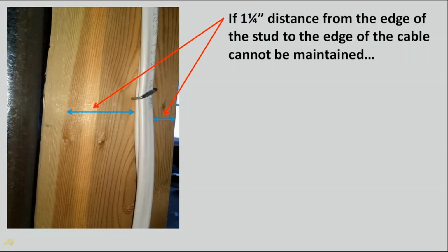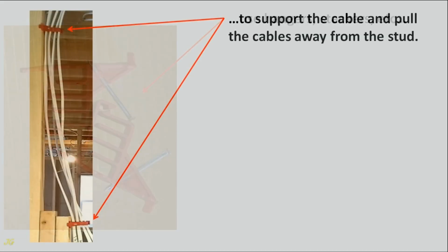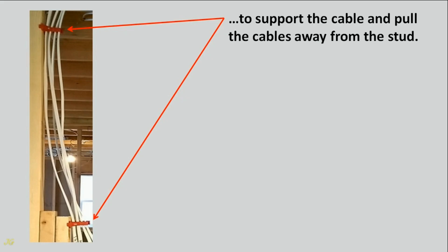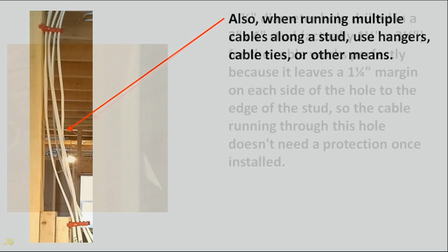If 1 1/4 inch distance from the edge of the stud to the edge of the cable cannot be maintained, use hangers, stackers, etc. to support the cable and pull the cables away from the stud. Also, when running multiple cables along a stud, use hangers, cable ties, or other means.